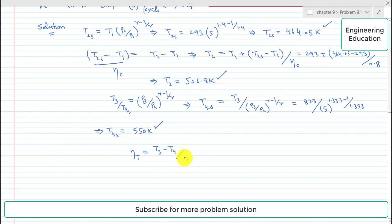So in this case we have T4 which is unknown, so from cross multiplication turbine efficiency will be multiplied with (T3 minus T4S) and it will become equal to T3 minus T4.